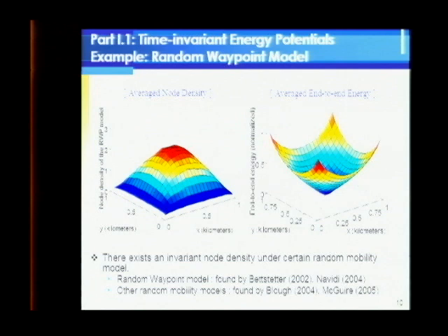In this case, when you're globally collecting it, it can be done as follows. From this location, when you initiate a beacon packet, you can cumulatively stamp that packet in terms of the cumulative energy consumption that packet has consumed so far to reach the base station. Once it gets there, that can be collected from the packet by the base station, but it's not available to the nodes. In other words, these global energy consumptions can be measured all the way by the base station, initiating the packet here, but it will be very expensive to spread it back to the nodes. So I'd like to be able to construct this, if possible, using only local techniques, without having to go all the way to the base station globally.